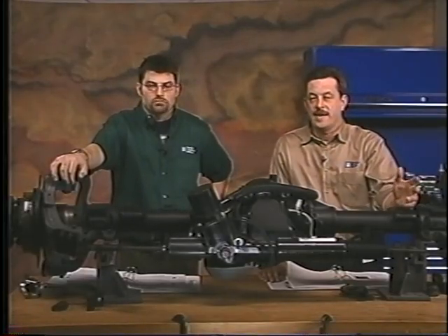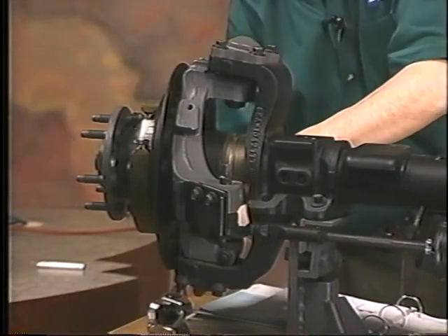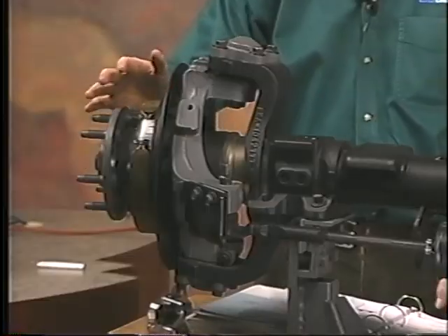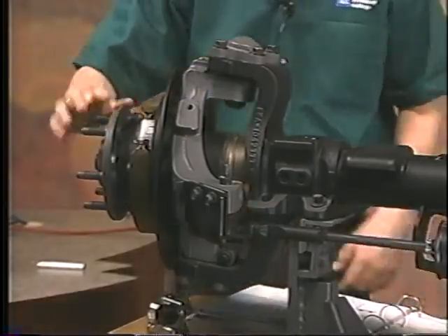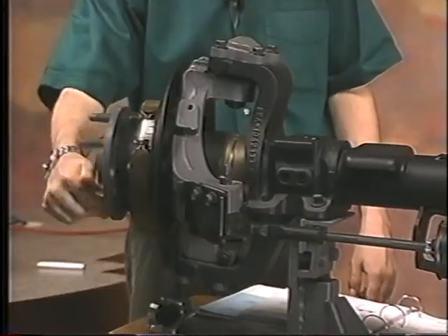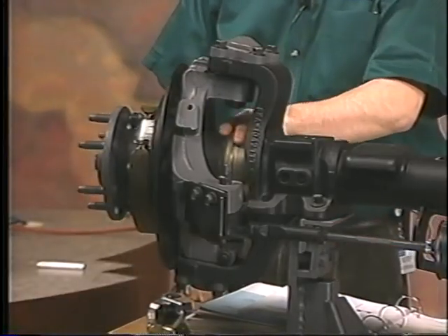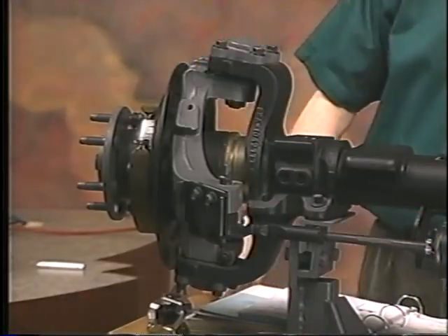Now, first off, what do we got? Well, we've got ball joints here. See those upper and lower ball joints. Definitely different. And we've got the spindle in between those two. Now, on the outer edge there, we've also got a wheel bearing. Again, not typical. It's very much like our front drive wheel bearing. Same idea there. We also got to have a quarter shaft. They call it a quarter shaft because it only has one universal joint in it. And it's pretty well protected. It's in there, you can see.